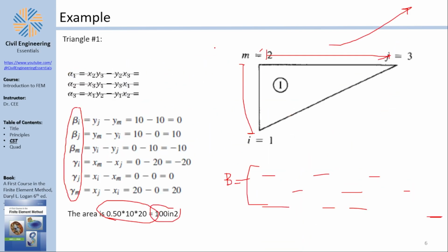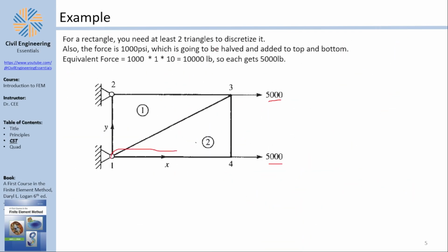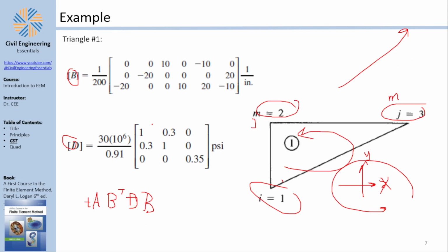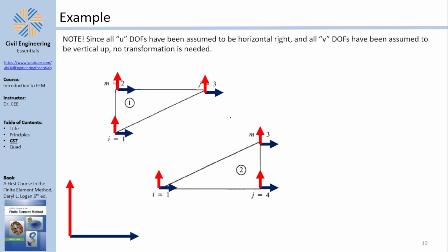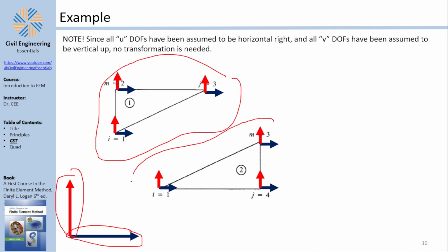You see, in the beginning, he's giving you this sneaky, almost hidden global x-axis, and this sneaky, almost hidden y-axis, and our assumption for our displacements were the same as the global axis. Don't believe me? Here is a clarification slide I have for you. The global x was going to the right, and the global y was going up, and the definition of the degrees of freedom of those triangles were the same.